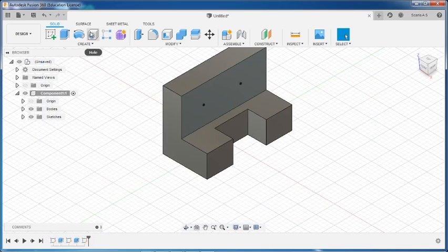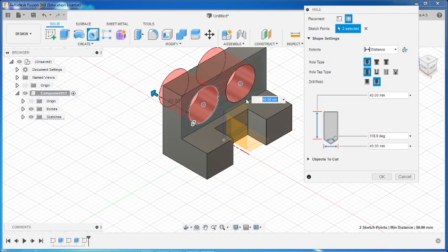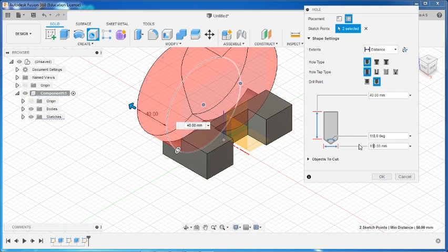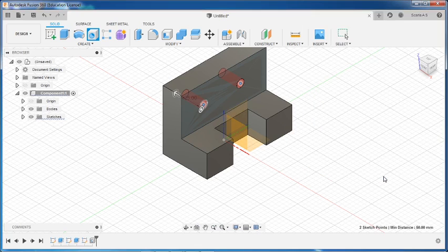So now you can hold the command key, then click this point and this point here. Directly you can select 2 points. So the diameter is 10. It is given 10. Then the dimension we have to change is already mentioned because we are selecting the points over there. So you can change this to true, then OK.